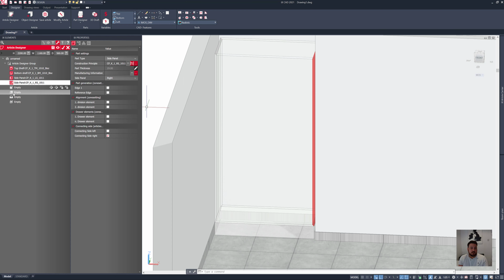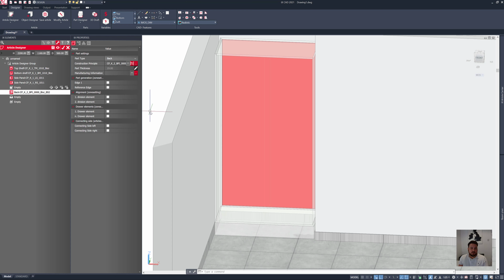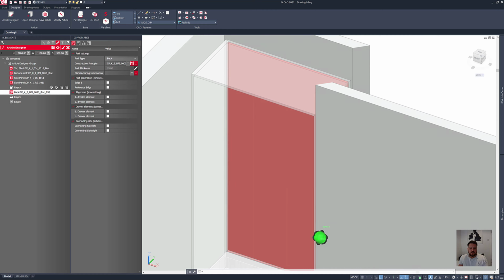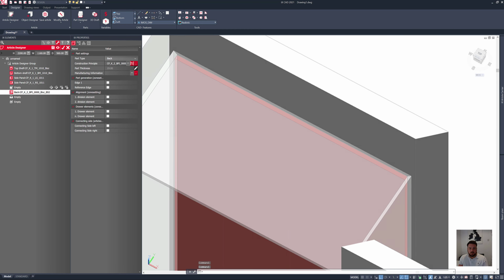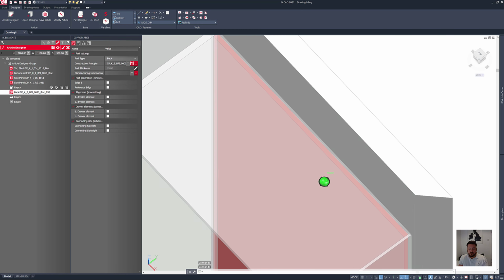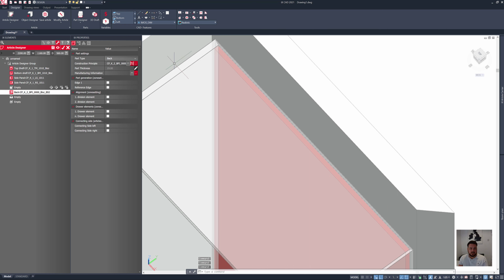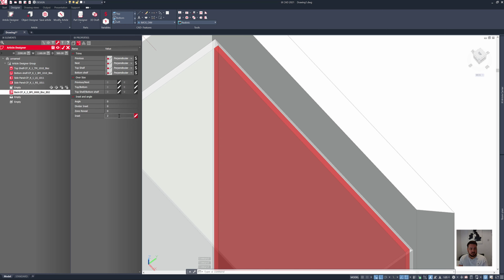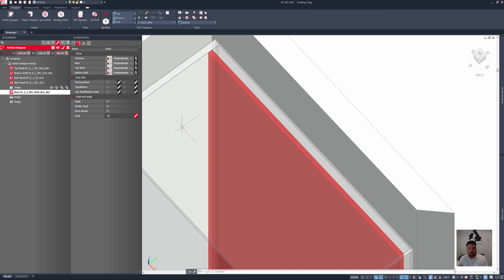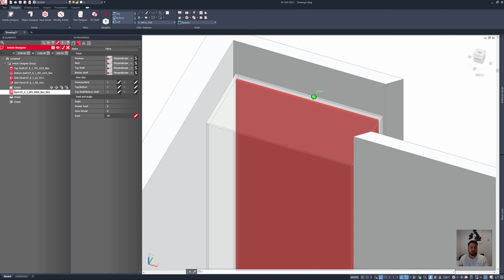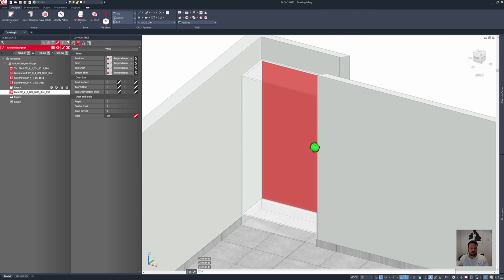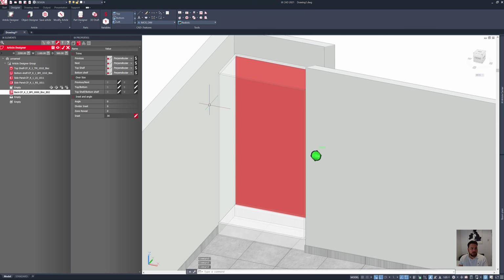The next step in here is to put in a back, so I can do that as well. And in here, if I want to, I can now orbit and zoom in nice and close, so I can now see in the 3D model exactly where my back is, and I can then, if I want to, increase things like the inset. So I'll just say that this should be 30mm inset, and you then get that live preview on the screen. So that's my back now brought in, which is nice.